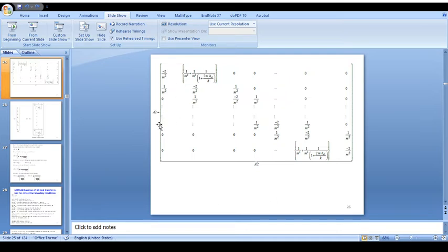We will compare the previous matrix A1 with this A2. Here you see these elements, all diagonal elements are the same. The off diagonal is also the same. This is also the same. The only thing that has changed is in the first row, second element, and the last row, second element. So these two have been changed due to the boundary conditions. These need some incorporation from the convective heat transfer flux.